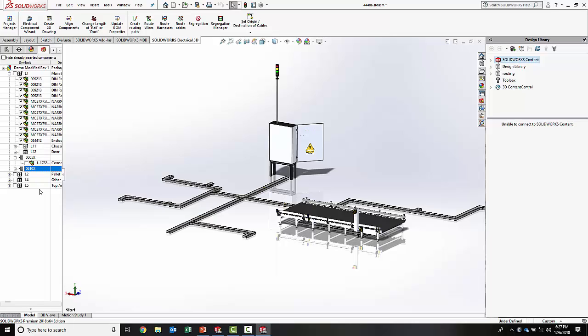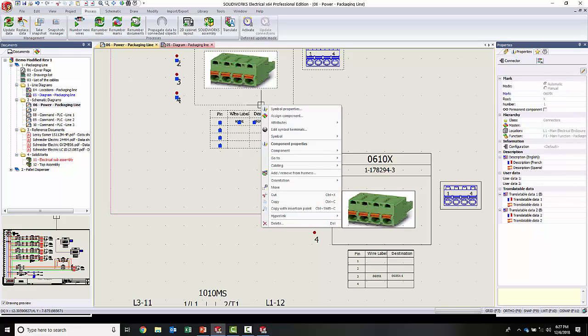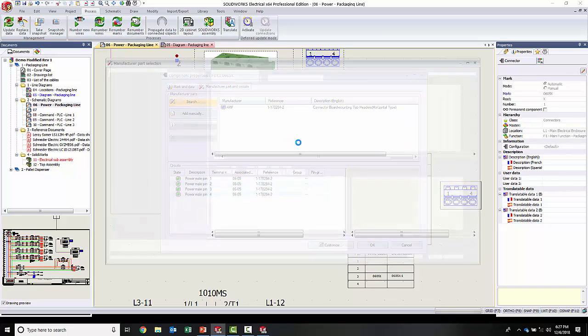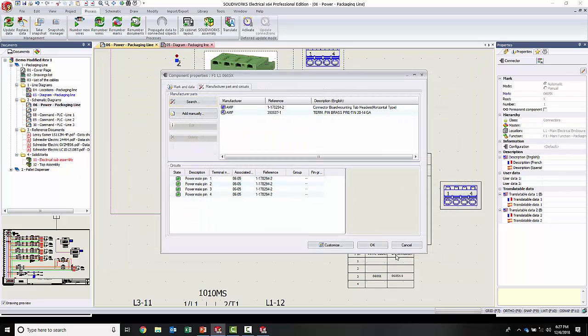Because of that, if I add another device or add a component to that device, it's also going to give me another 3D model. So if I were to go back to schematic and take that device and add a second part to it, it doesn't even matter what that part is. If I search and just grab another part, so I'm grabbing an auxiliary here, we'll just grab a pin, and I'm going to add a pin to that so that I have 2 parts.